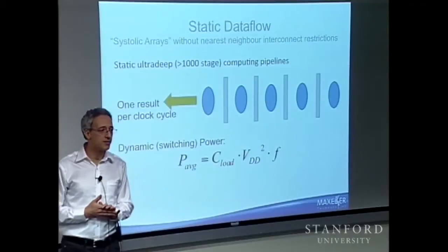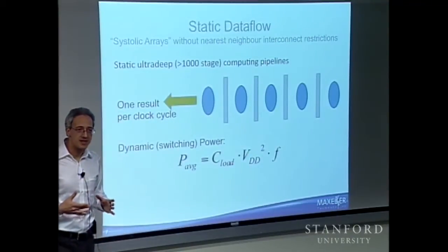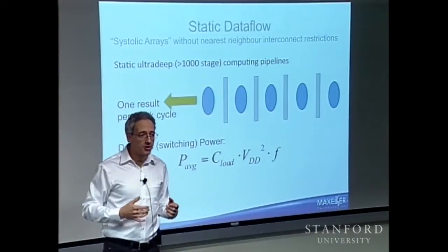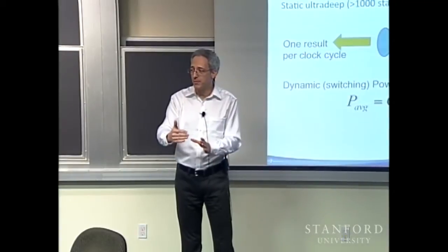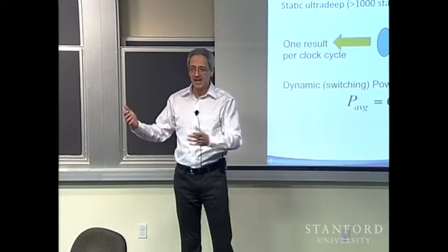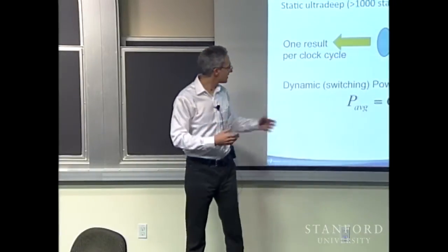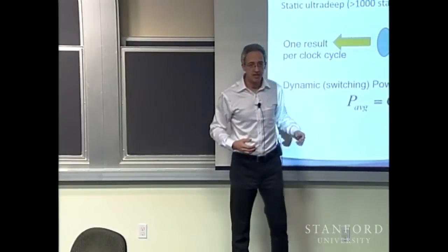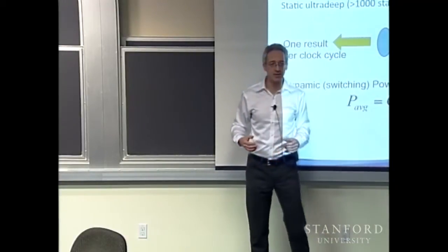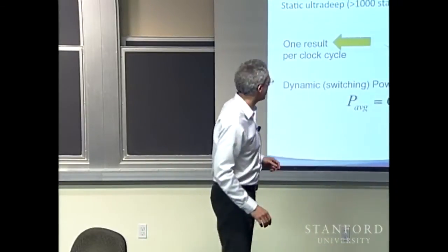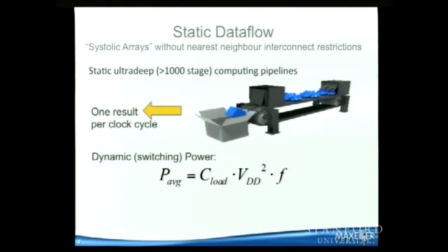And so then all you have to convince yourself is that the largest chip that you can buy from most major companies today are driven by whatever can be manufactured and put into a package. So the largest chip from company A will probably be as large as the largest chip from company B. And that will set the capacitance, and then one can argue around about the voltage here a little bit, but I won't be doing that too much. My argument is really more about the clock frequency being minimal, and for a set of capacitance and voltage, that gives you the minimum power consumption here.